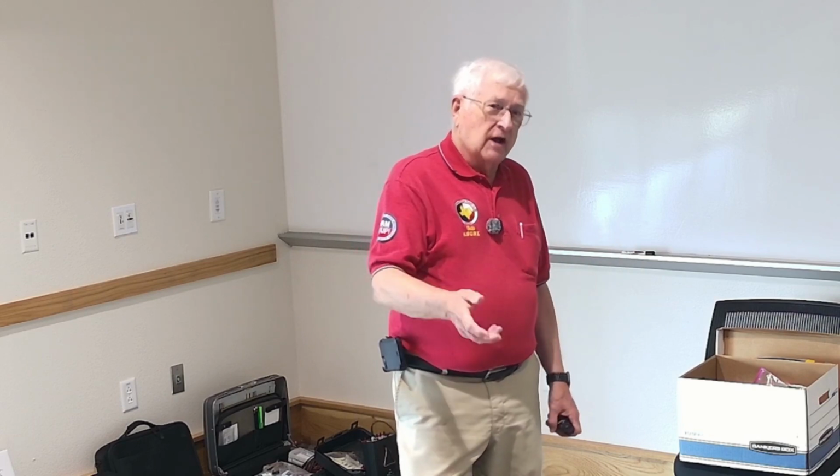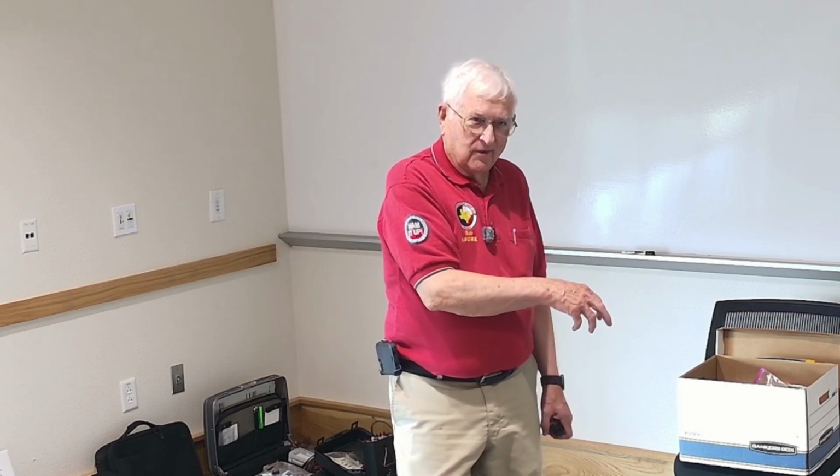Plus, inside the radio, DC is a solid line. How are we going to generate a 144 megahertz signal with DC? Can't do that. You've got to convert it with something else. So we use the DC to power an oscillator, which generates the frequency we're looking for, which is AC, and then it gets distributed through the radio and all the way out to the antenna. And the same thing coming back in.